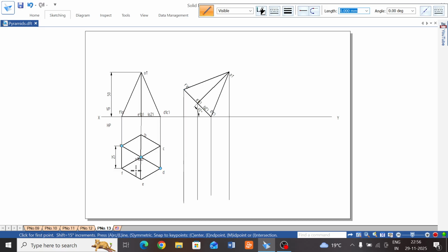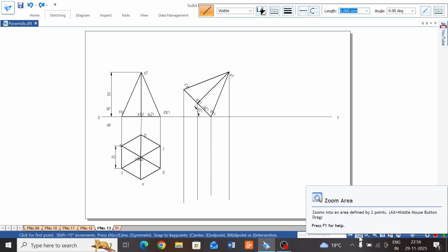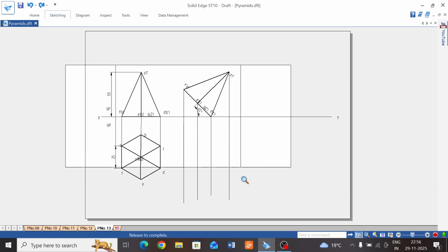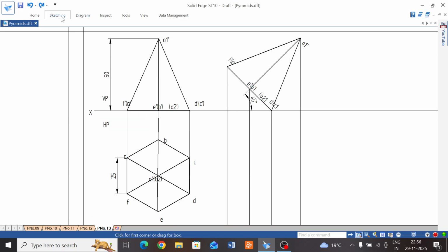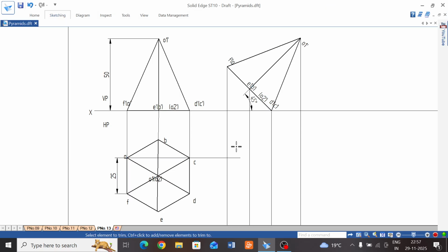Now project this. The first point here will start with A, up to here only. Okay, it has to be exactly 0 degree. Check that the line must be 0 degree, and you can use the zoom command. You will get a better picture. Okay, go to line, thin line. Here A end point, single arrow, the A dash, 0 degree. It's showing the angle is 0. If it's not showing, it means the extent, and you can trim this end. Okay, this is A point.